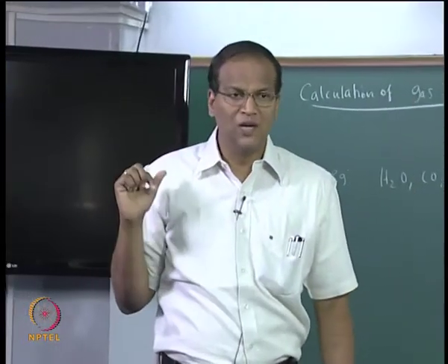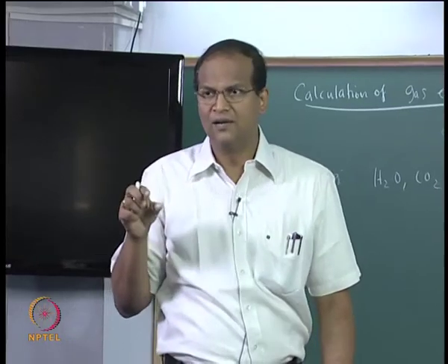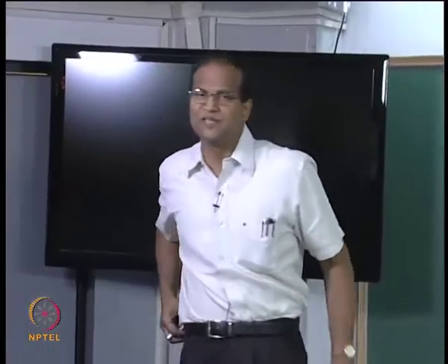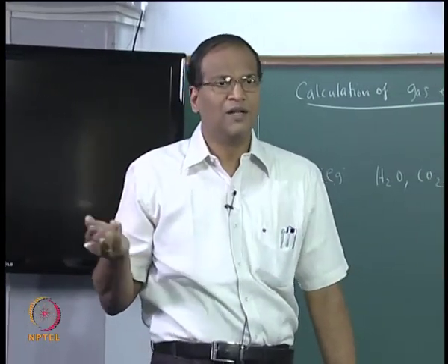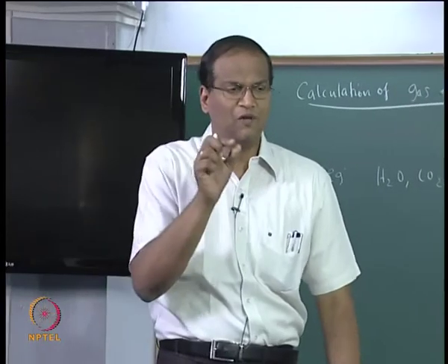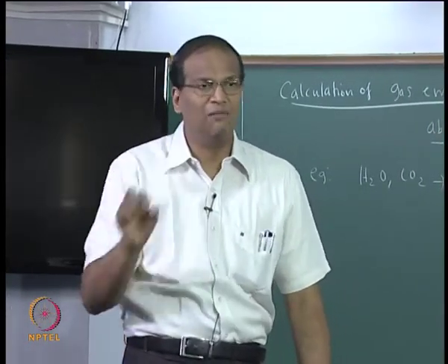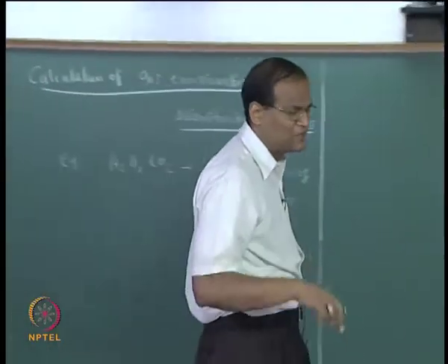So, if you want to do a detailed calculation, you have to solve the equation of transfer for every spectral band, knowing the properties absorptivity and emissivity, which must come from molecular spectroscopy, and then solve it band by band or interval by interval. So, it is called a line by line model. I already told you that it is very advanced, it is very time consuming.